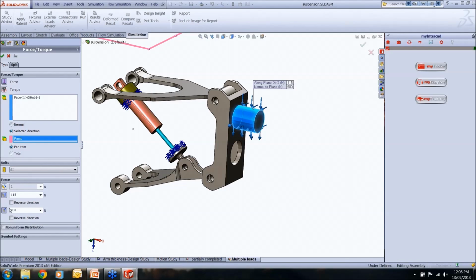Now, from this point, we are starting design optimization exploration study. These values are absolute values. However, we can set them as a parameter, and later on we can specify a range of variation. How we can do that? Whatever initial value you put there, if you just expand this, there is an option to link the value.